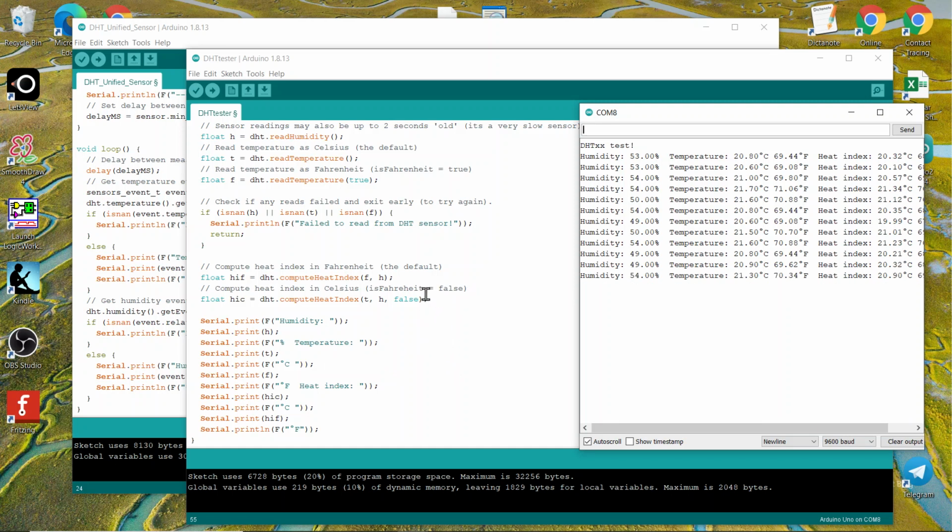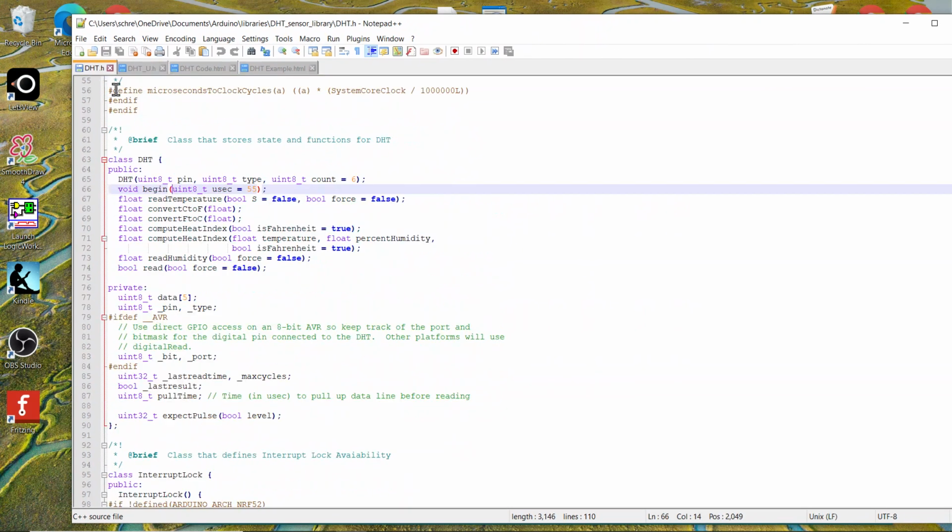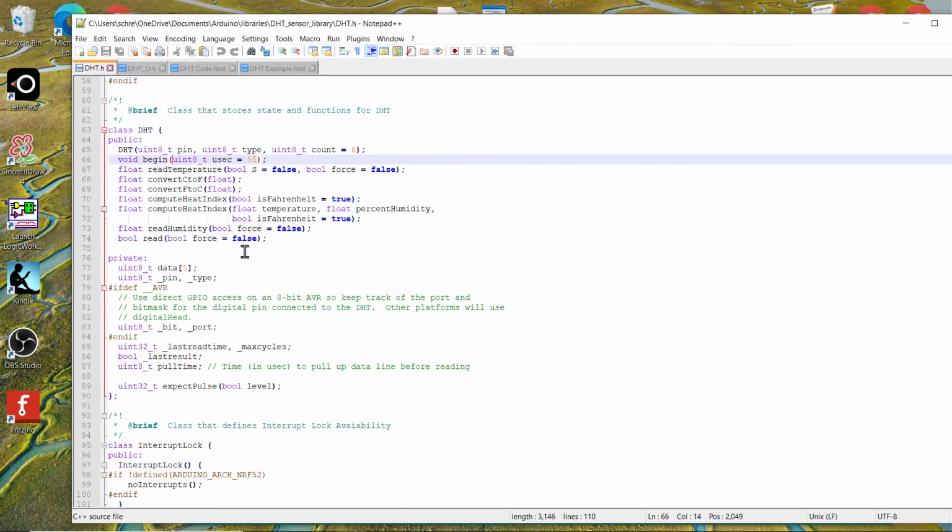So that gives you a little bit of an introduction to the complexity. By the way, if I drag this one down here, I thought in one of these library files I saw a convert. On line 68 here, you see float convert C to F. So there is a function that's already defined by this library to do the conversion, and I just follow this format, put it in there, and it'll do a conversion for me.